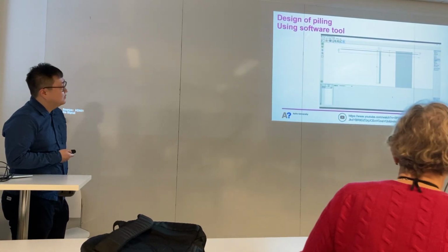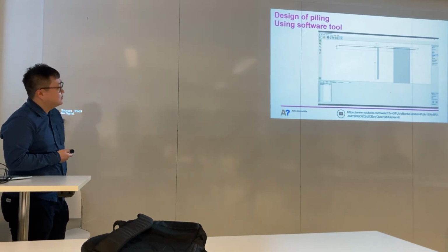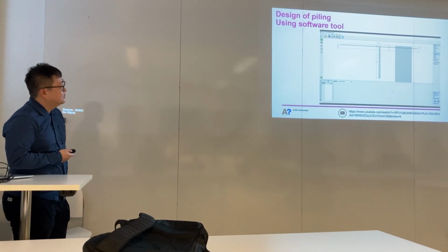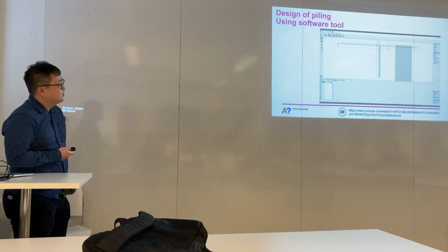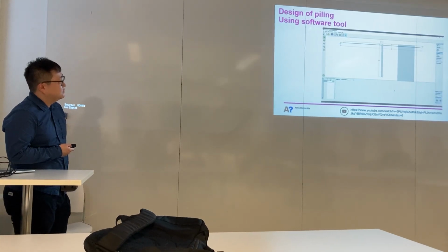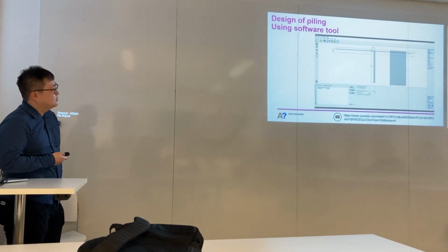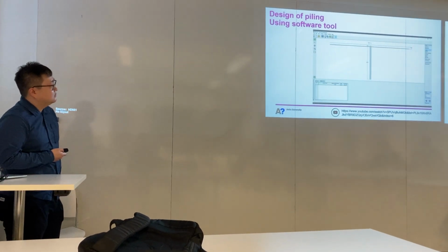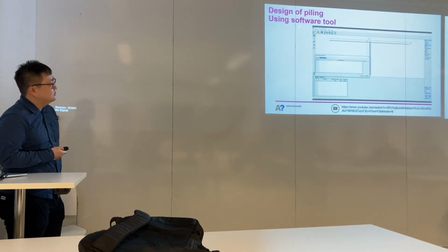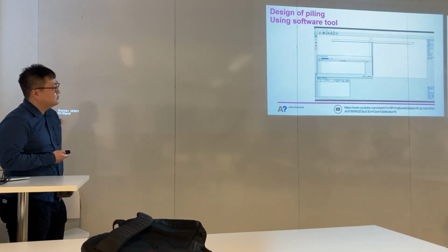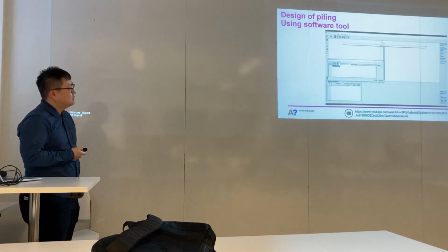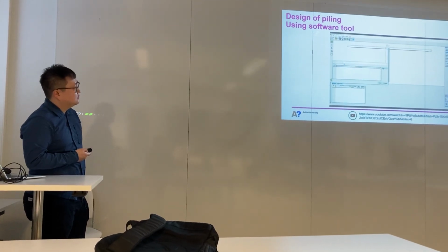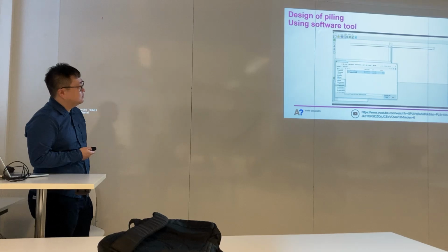This tutorial shows how to design a pile based on the cone penetration test, or CPT. We will perform an analysis according to the Eurocode standard EN 1997-2. Firstly, we must check that we are proceeding in accordance with the Eurocode standard, which can be set in the settings screen. Then we load the CPTs, which are our primary input. The tests can be imported in different formats, either text format or other defined CPT formats, such as GEF. In our example, we will use the Dutch GEF format.